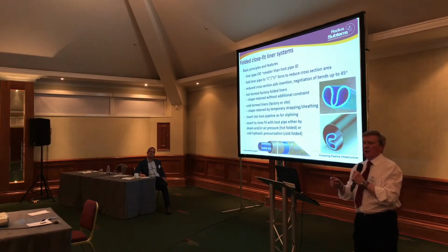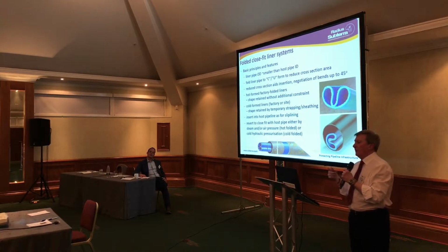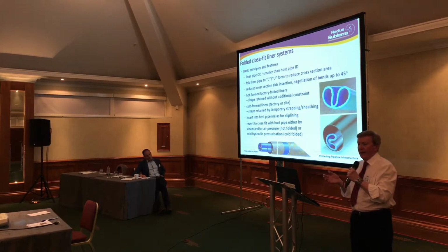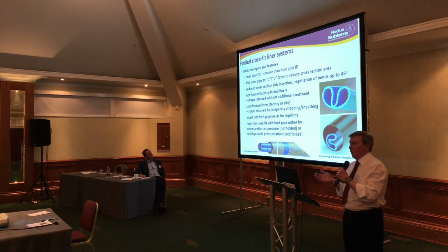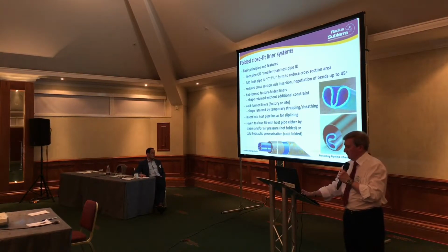Once the liner's slip-lined into place, the ends are opened out and the shape is reformed, and that could either be with a combination of steam and or air pressure for the hot folded systems, or it could be by cold hydraulic pressurization for the cold folded systems.